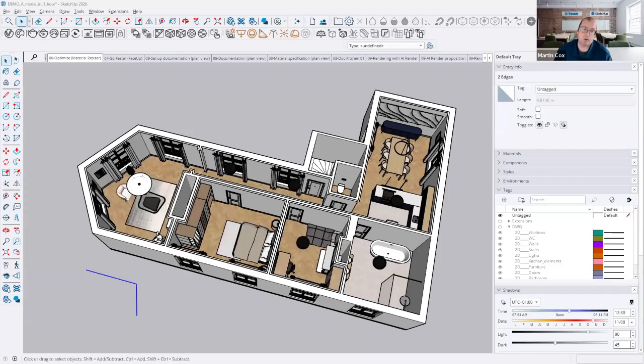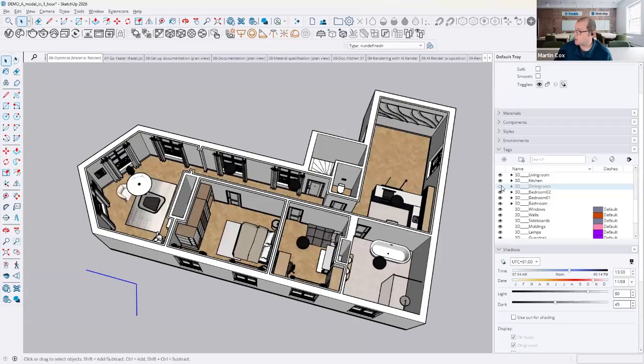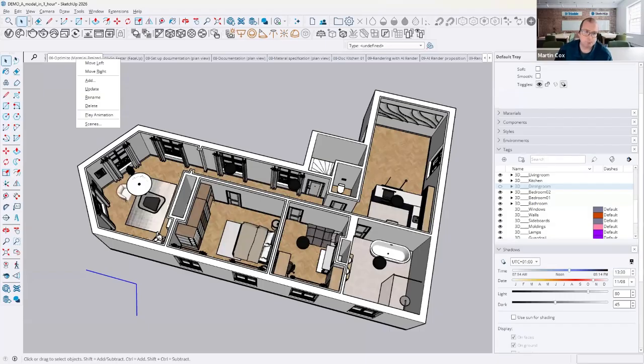It really is, yeah. So it is around updating those scenes, so turning things on and off within tags. Within 3D here, everything's nicely managed in tags. You can even have tag folders, which are brilliant because then you can turn multiple things off. If I turn off what's in the dining room there, I update my scene. I can either right click on it and choose update, or I can do this from the scene manager, and that will update my scene with the furniture there. Okay.